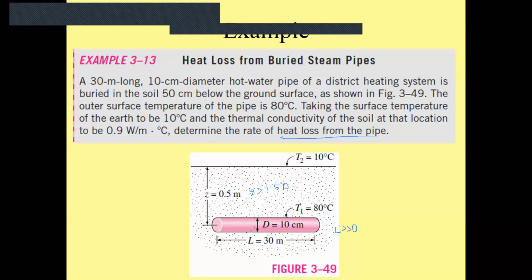That's why you can use the conduction shape factor. If you remember, the equation is simply S k (T1 minus T2). This is the general equation for the conduction shape factor, to calculate heat transfer by conduction.